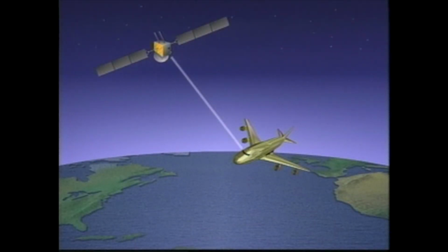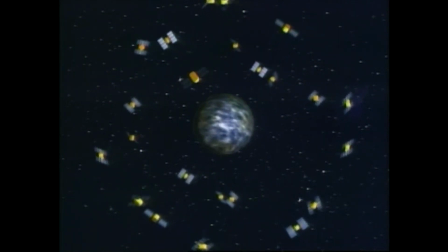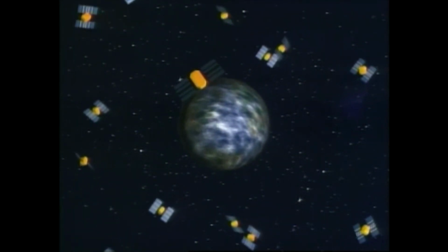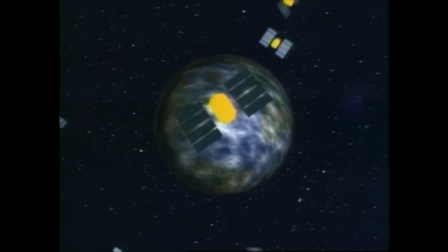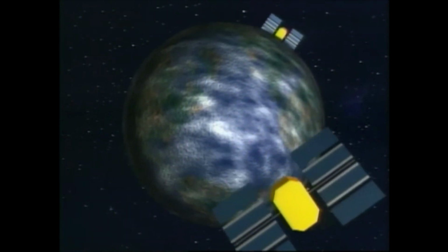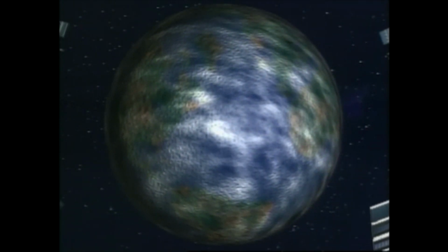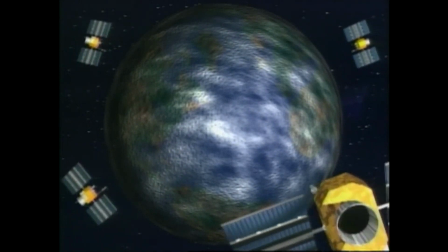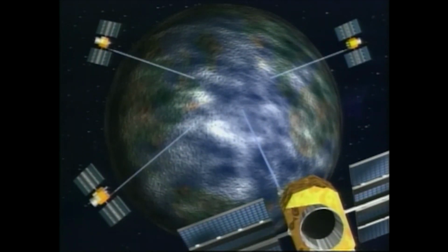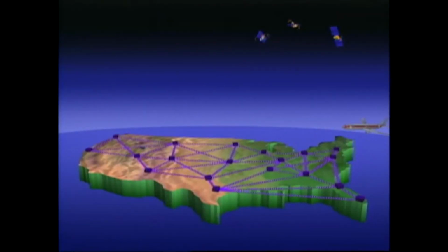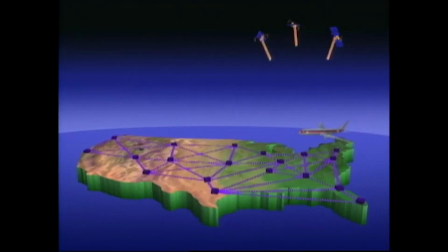Basically, GPS is another time-of-flight technique using radio waves. But the transmitters are mounted on a constellation of satellites which orbits the Earth. Right now there are about 24 satellites in the constellation, and they're designed such that at any one time you should be able to see somewhere between 4 and 8 satellites. A computer in the receiver knows where all the satellites should be at any one time, so by measuring the distance to several satellites, you can figure out your location.